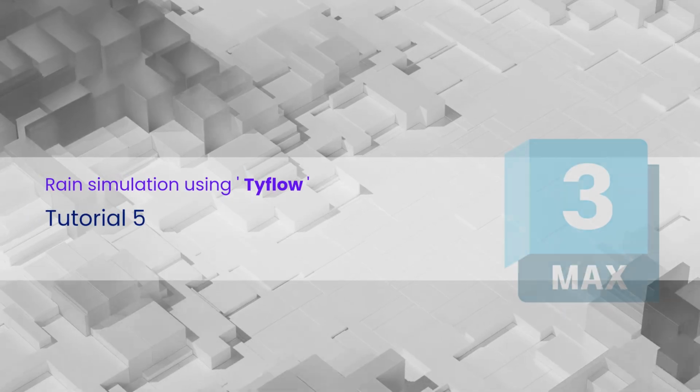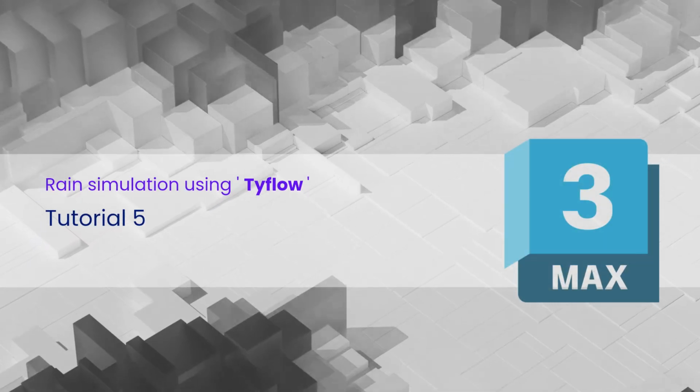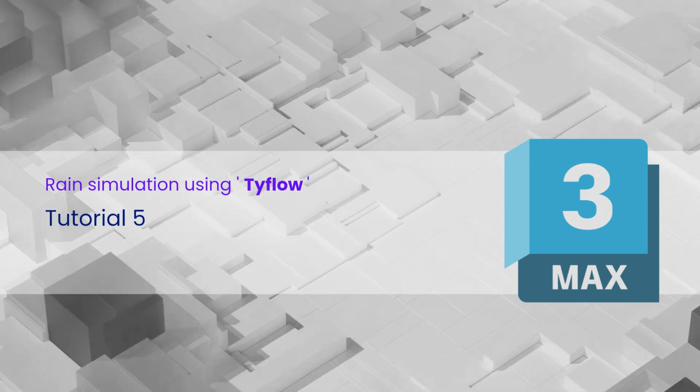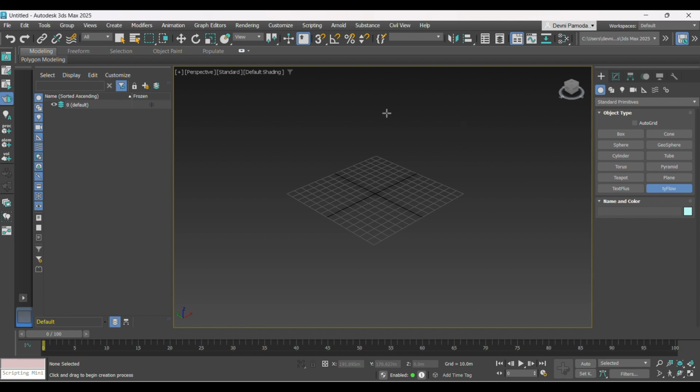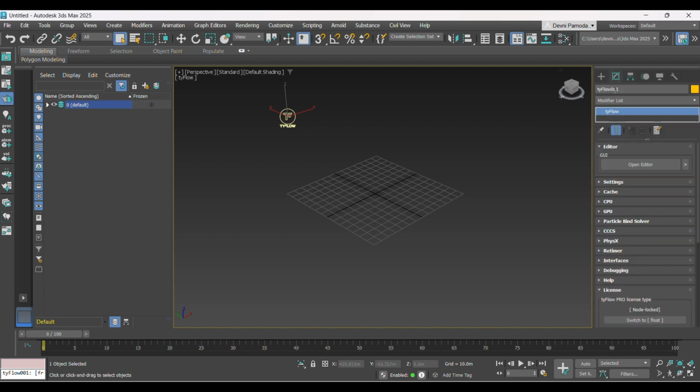Hello everyone, next we are going to explore Tyflow to produce a rain simulation in 3ds Max. For this exercise, we need to download and add the plugin for Tyflow. First, we insert the Tyflow icon onto the screen and then move to the Modifier tab to open the editor.